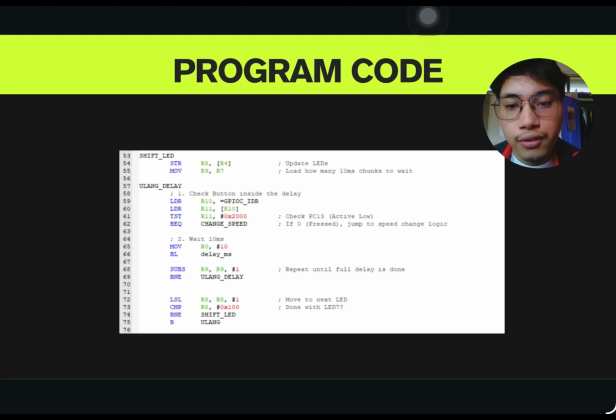For the first one, we load the value of input R10 into R11, and then we test the value of R11 for the value of 0x2000. This is essentially just to test for the button press. This is essential for the CPU to read if there is a button press. It is quite the same mechanism as the first part, where we wait for the button press.